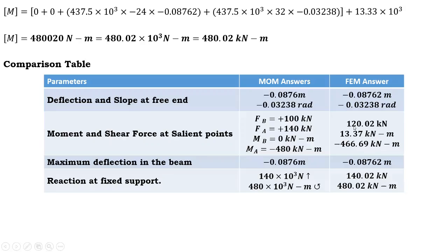But when you consider the addition or deletion of those according to the sign, I'll get the same value because I have a shear force of 120 kilonewton, and these are the two moments which are acting at the free end as well as at the fixed end. I have only one shear force, that is the average shear force, which is there in the beam. That value is 120 kilonewton.